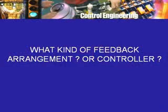And therefore, of course, we thought that it was not good, or it may not be good in some situations where the resulting steady state error is not acceptable. But now that we are introducing this element of feedback, of manipulating or making adjustments so that the error may be transient, our controller must be such that there is no longer any steady state error. In this context, we will look at the Ward-Leonard type of control system and at what kind of feedback arrangement one may use, and see that it is possible to make the arrangement in such a way that there will be no steady state error after the load condition may have changed, or some parameters such as the field current may have changed for things beyond our control.